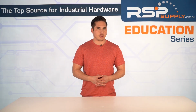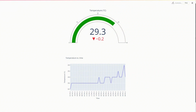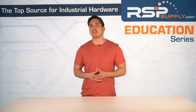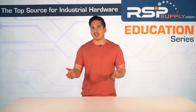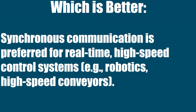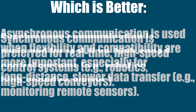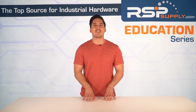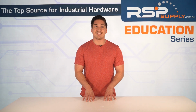An example of this in automation: let's say you have a SCADA system that's retrieving sensor data from a remote RTU over Modbus RTU. The data is sent in packets without a clock signal, making it flexible but slightly slower. So which is better for industrial automation then? Synchronous communication is preferred for real-time, high-speed control systems like robotics, high-speed conveyors. Asynchronous communication is better used when flexibility and compatibility are more important, especially over longer distances. There's going to be slower data transfer, and it's going to be used for monitoring remote sensors, for example. Both methods are essential in automation, depending on the system's needs.